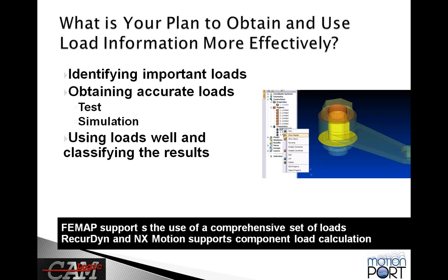And it is possible for there to be errors both from a simulation point of view or from a test measurement point of view. Test equipment can fail or give poor readings due to some issue that may go on. It is possible to not get good results from the simulation if the model doesn't include all the important aspects. So if you use these two things together, the physical test and the simulation, once you start getting agreement between the two, then you can really have good confidence, because the sources of error for the two different techniques are different. So the idea is that once you get things to match, that means they both must be giving correct answers.